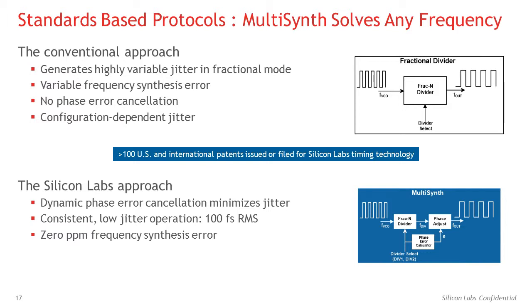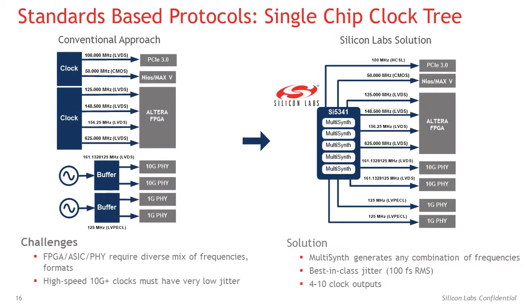We still keep that phase jitter very, very low, whereas if you look at the fractional phase jitter in most data sheets for different timing products, you'll find out that when you have to do fractional stuff or odd frequencies, it really messes up the phase noise. So then you have to resort to many different devices. And really, the real-world application of that is that you can then use just a single chip and hit all of the frequencies that you need and still hit all of the specifications that you need.